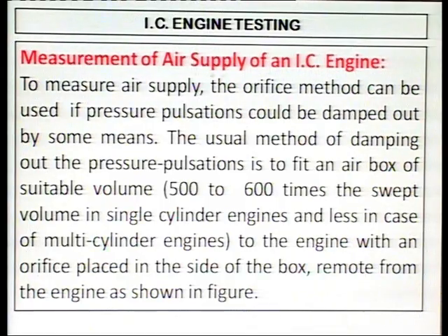Measurement of air supply of an IC engine. To measure air supply, the orifice method can be used if pressure pulsation could be damped out by some means.